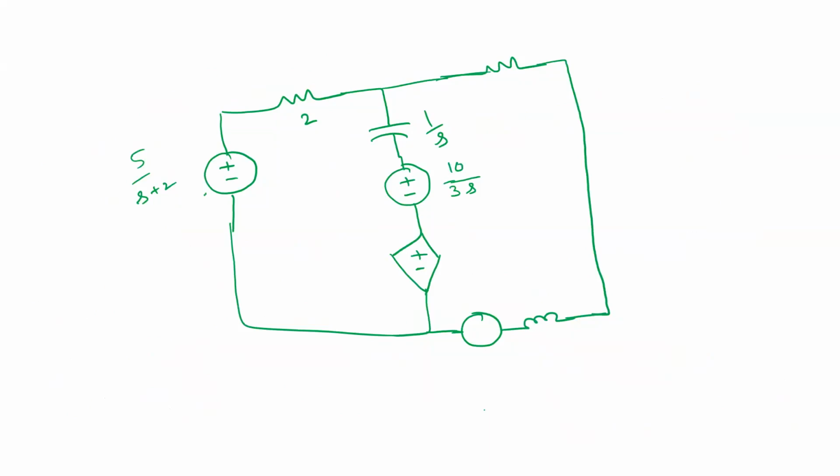Okay. So next we have this 1 ohm. What is its value here? This is the voltage V naught, so its value is 1. What is the Laplace of this one? It's just 0.5 V naught only. So no change here. Because if there is a change here, automatically it will change here, right? So just replace with 0.5 V naught, even in Laplace.